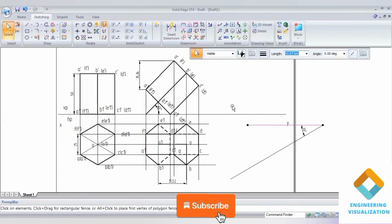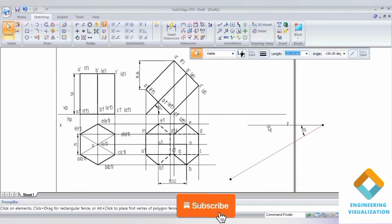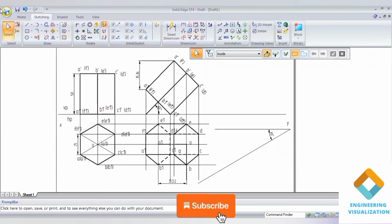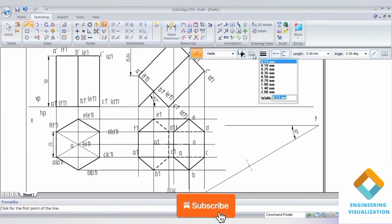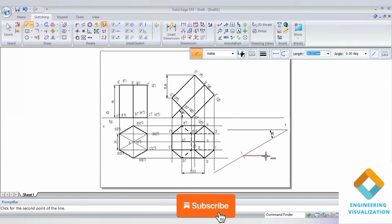Okay, select this entire thing and then you can move it. First an arc length of 50 mm we have to cut. Okay, 50 mm cut the arc. So draw the locus line.